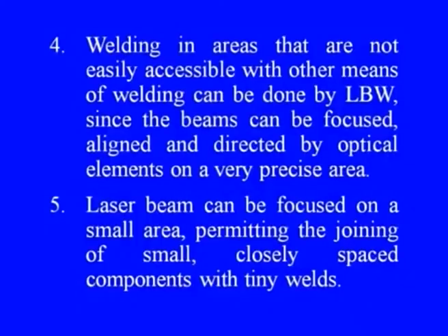And of course, the conventional welding rods will give a macro level welding spot, which can be reduced to a very narrow or small zone in case of laser welding. Therefore, it is suited mostly for micro joining or micro manufacturing applications. The laser beam can be focused on a very small area, permitting the joining of small and closely spaced components with tiny welds. Ideally, it is suited for most micro fabrication purposes.